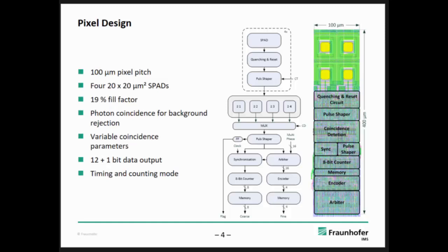And this output signal here is given to the TDC, which is built of an 8-bit coarse counter for coarse time measurement. It's just counting with our 200 megahertz clock. And a time interpolator to measure the time between the start signal and the next rising edge. For this, we are using a DLL on a global level and delay our clock signal in 16 steps. And these 16 steps, or the 16 phases, are frozen by the use of arbiters. And from the states of these clocks, we can calculate the actual time.